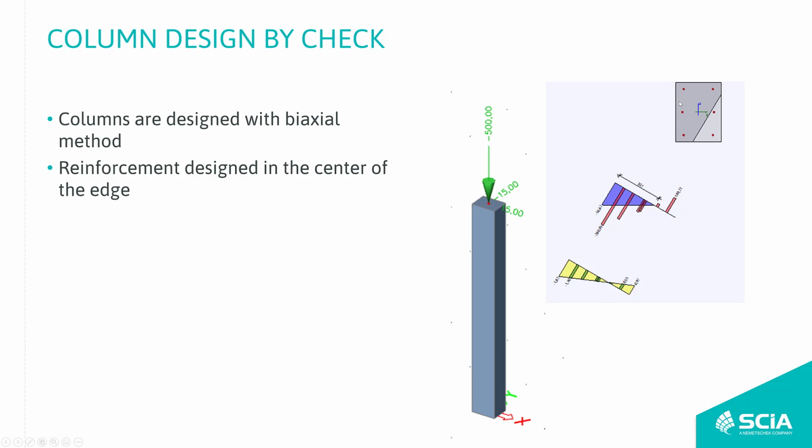This is the state and the plane of the deformation, and the algorithm for the design counts with the fact that the reinforcement is placed in the middle of each edge. As you can see here, it's not optimal because the center is here, there, over there, etc. And it could lead to a big amount of reinforcement just because of the fact that there is some